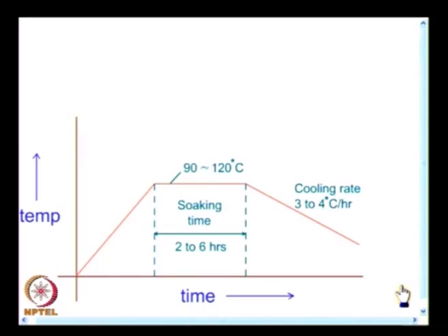So, the stresses are locked, and in the deformed position the primary bonds remain. So, when I remove the load, the stresses indeed get locked. We will see that by an example. We will take the circular disc under diametric compression. We will look at how the fringes develop when the model has gone through a thermal cycling process.